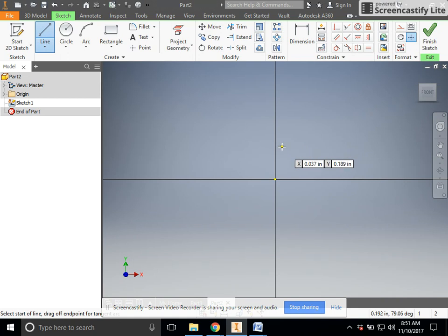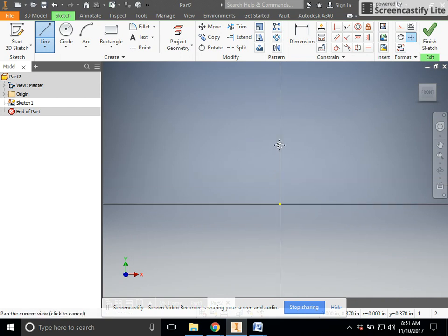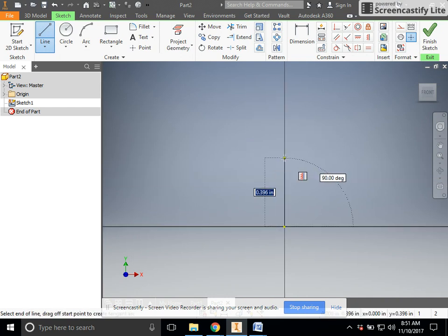schematics. I'm going to talk about how the schematics are also a little bit incomplete, but I like to start in the middle where the two pieces come together, the two profiles come together. I'll start in the origin. Maybe you'll see what I'm working with here in a second. But this first line will go up the smallest diameter, and I'm only drawing half of this, so I'm going to cut it into radius. So we have 0.19 divided by 2.